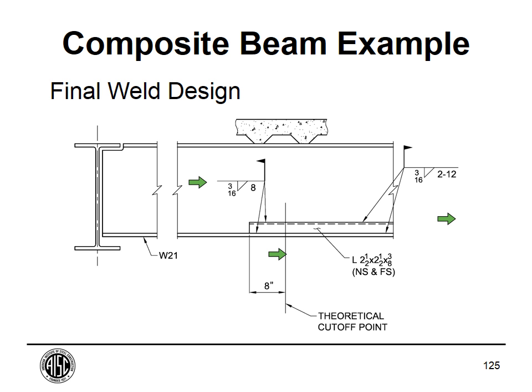Really quickly, one other way to show these welds is, if you're showing a cross section instead of the side of the beam like I've got shown here, you can eliminate that weld and put a tail on this weld and just write in the symbol that I've got shown there and put in the tail 8 inches continuous at ends.